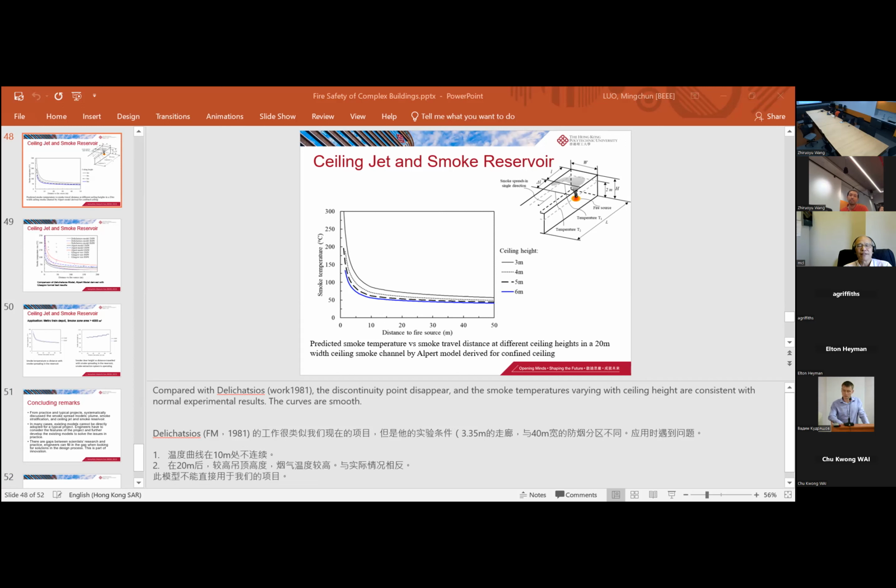But for the design of a smoke extraction system, the extraction rate, or how big a fan you need for a building, you either specify it based on the regulation, which gives you some method to calculate the extraction rate, or use the plume model introduced here. You use a plume model because you know the smoke clean height, and you can calculate the smoke extraction rate you need. But the CFD model doesn't give you this figure.